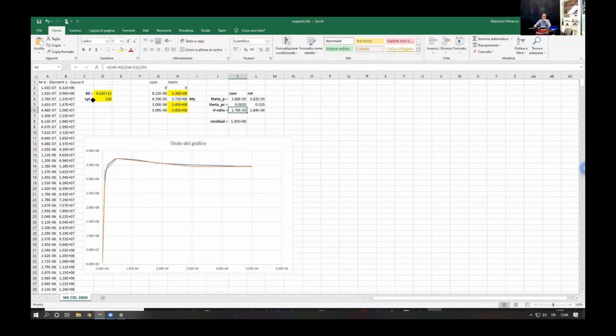In this example here, when you take the stiffness from the moment curvature, it will give me the exact elastic stiffness of my cross-section in terms of moment and curvature. But since this one is zero length interface, and since the elastic response is already given by the entire beam, it is better to consider this one some orders of magnitude larger than the elastic stiffness, in such a way that it doesn't interfere with the elastic response of the rest of the element.